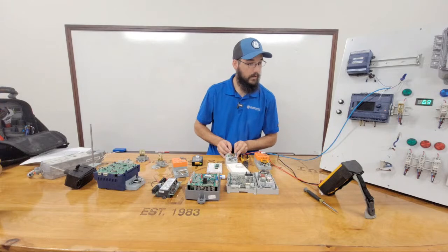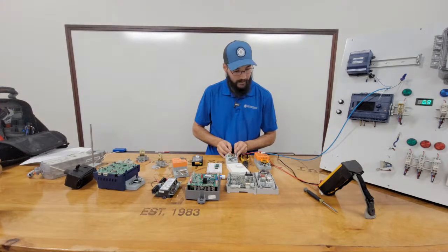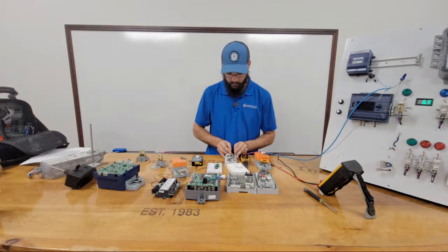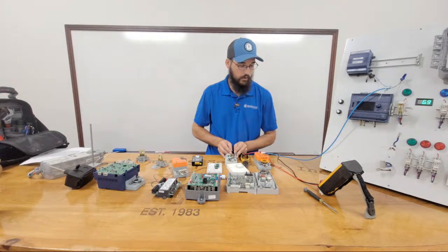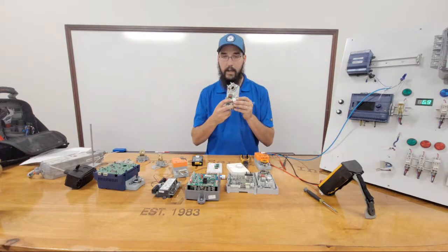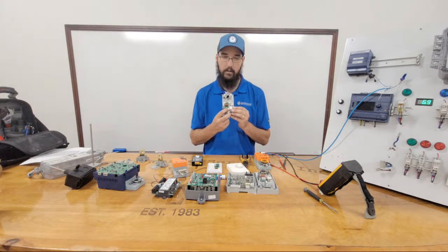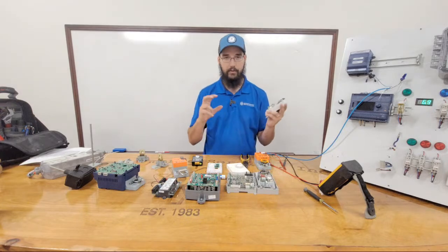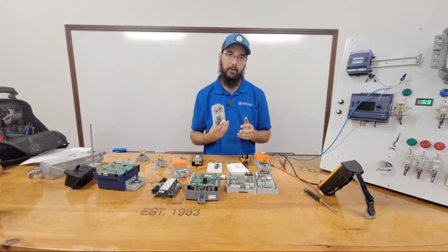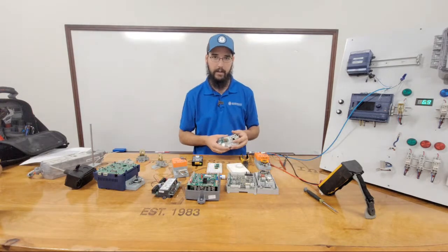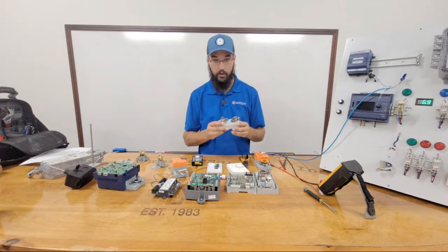So it does. If I go between terminals 1 and 3, I see 486 ohms. If I go between terminals 1 and 2, I get 490 ohms. And that's what I would want to see. What I just read is the stator on that tiny little motor, and those should be identical. Now, I don't know what the factory tolerance is on that motor, so I can't tell you that. And it's going to be different actuator to actuator, so don't think that 490 is the go-to.